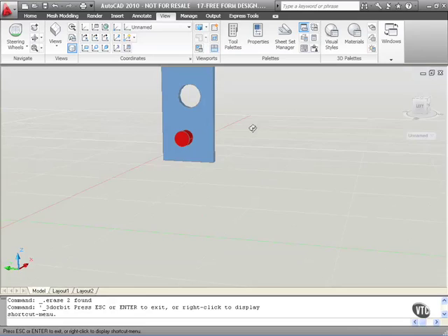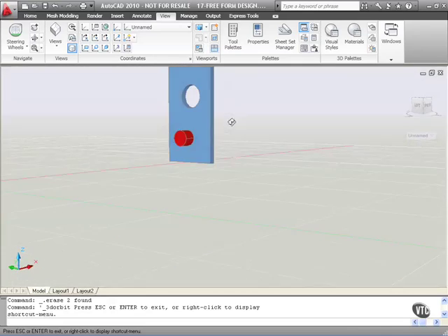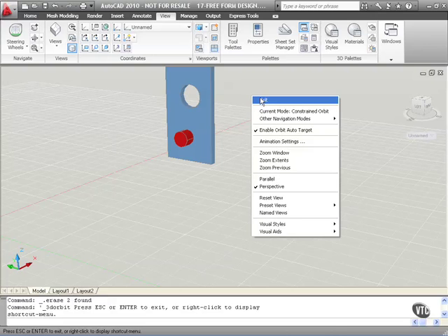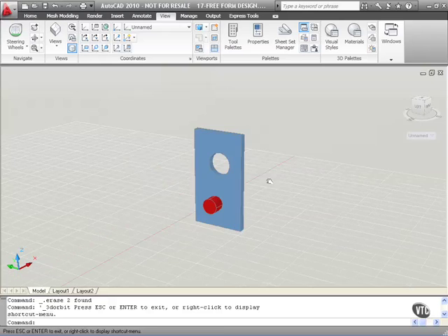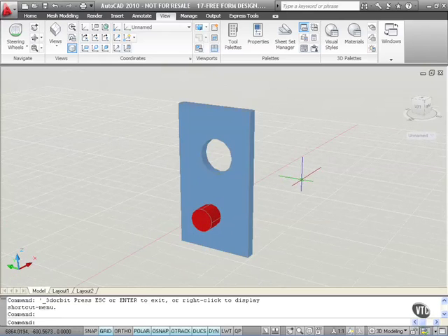So as you can see there, you can see my rotated shape there. My cylindrical surface is obviously touching onto my rectangular surface there, and I've got my hole in my rectangular solid where I used the dynamic UCS. I right click and exit the orbit, and then I'm back to my normal crosshairs there, and I can just now pan holding down the wheel and zoom in and out using the up and down on the wheel like so. So as you can see there, basic freeform design in AutoCAD 2010 can be done in a couple of minutes, as you can see.